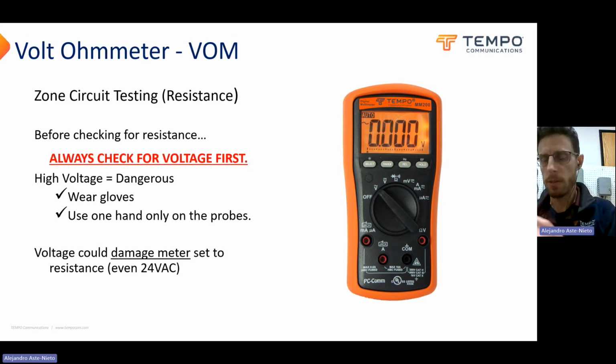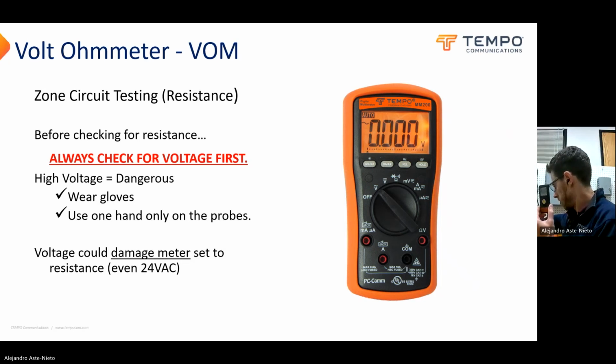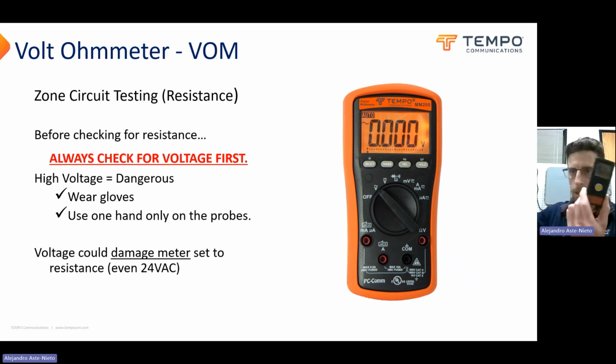The battery here, we're going to see 9.63 volts there. I don't know if I have any AC plugs within reach. Let me see. One hand on that. Not sure how well that'll show up, but that's 119.8 volts, 120. So it'll do DC or AC voltage, or if there's no voltage, it'll tell you the resistance. It'll tell you the ohms. Pretty nice little feature there on the PM100.